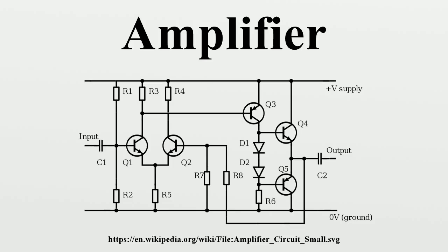In practice, amplifier power gain depends on the source and load impedances, as well as the inherent voltage and current gain. A radio frequency amplifier design typically optimizes impedances for power transfer, while audio and instrumentation amplifier designs normally optimize input and output impedance for least loading and highest signal integrity.